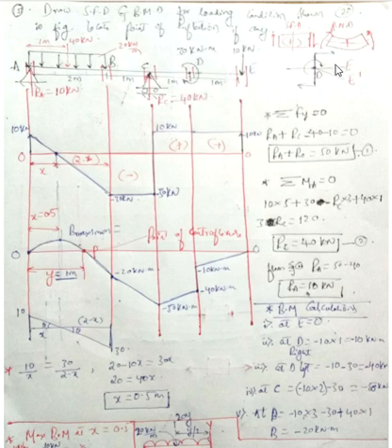See, this horizontal section is a beam, and if we consider a vertical link connected to this beam and apply a right side force to the top section and a left side force to the bottom section, there are forces and there is a perpendicular distance. That means these two will form a couple moving in the clockwise direction. So this force into perpendicular distance is represented by this symbol and it is given as 30 kilonewton meter.